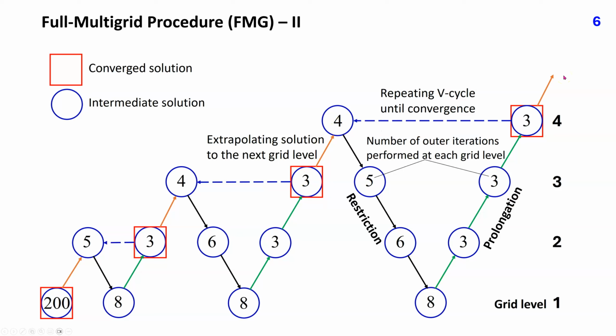The optimal number of iterations performed at each grid level is problem dependent. For lid-driven cavity flows, fewer iterations at each level are needed. The buoyancy-driven flow, to be studied in slides 15 to 23, requires more iterations due to stronger coupling between temperature, pressure, and velocities.